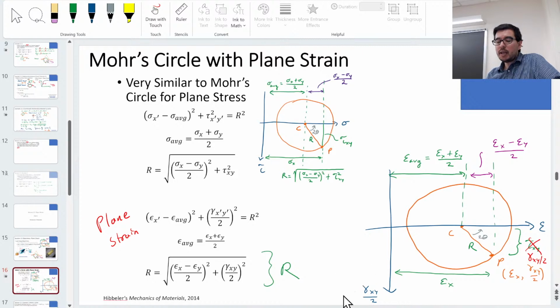This is now the second thing that can be confusing, because we have a 2 theta already in our Mohr circle. So 90 degrees on Mohr circle corresponds to the element rotating 45 degrees. And now what we're saying is that the gamma xy over 2 is what we have in the vertical direction. So when we look at maximum shear strain, we are going to get a number, the radius, that is actually gamma over 2 instead of just what the in-plane maximum shear strain would be. Okay. So those are 2/3 of what this session covers.